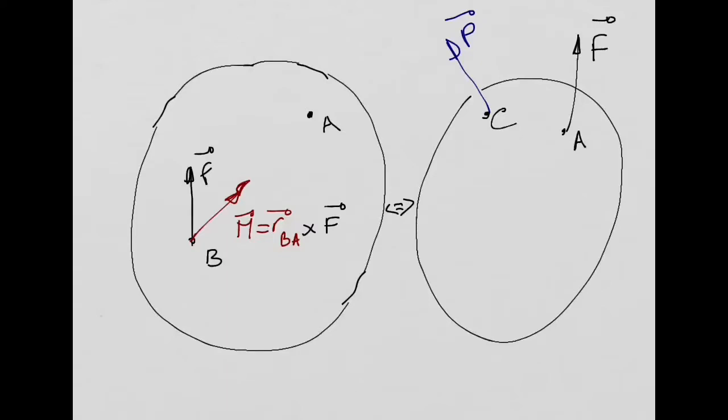So we transferred already on the left hand side the force from point A to point B, and we added a moment as well. I'm going to do the same for this force at point C, force P. So I'm going to include a force P here. So this is my P. It's the same force as I have at point C, but I need to add a couple.